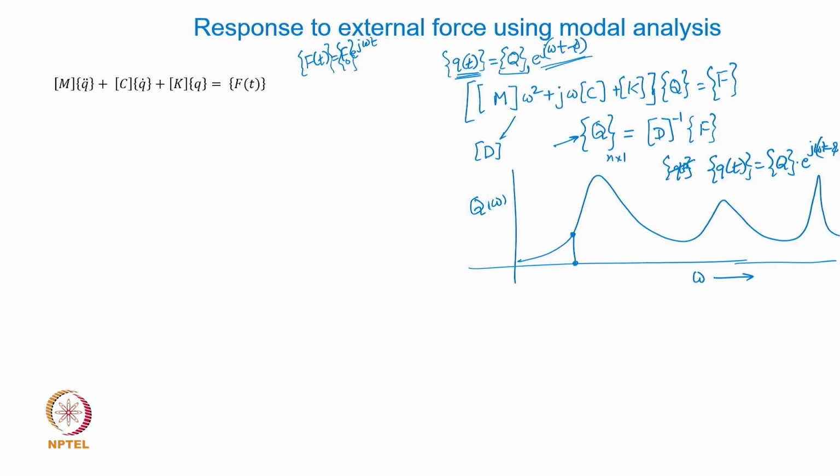For some other frequency I will get another one. So, this is omega 2, this is omega 1, countless number of omegas, right. If I change the excitation frequency, is this matrix the same? It is not, because this is dependent on the frequency of excitation. So, in the inversion process, I will have to do this inversion every time for every new frequency of excitation.